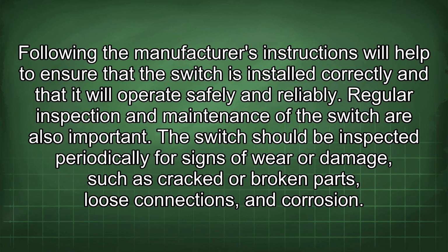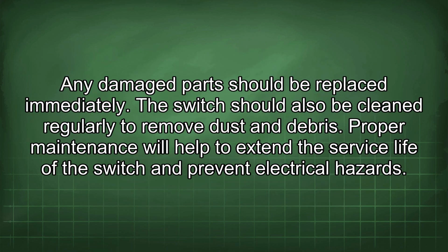Regular inspection and maintenance of the switch are also important. The switch should be inspected periodically for signs of wear or damage, such as cracked or broken parts, loose connections, and corrosion. Any damaged part should be replaced immediately. The switch should also be cleaned regularly to remove dust and debris. Proper maintenance will help to extend the service life of the switch and prevent electrical hazards.